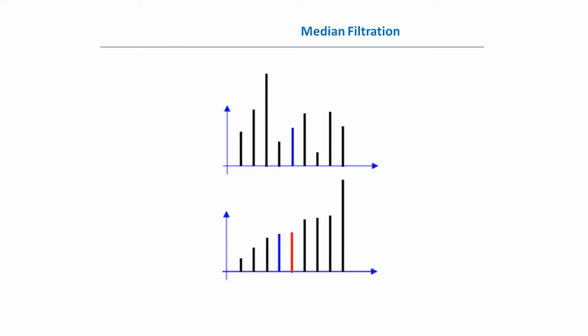Here is an example in the single-dimension case. At the top we have the input array, which has the central point we are filtering, and it has some surrounding points. The median filter puts these points in a row in increasing order of value, and writes to our processed point the median value of this set.